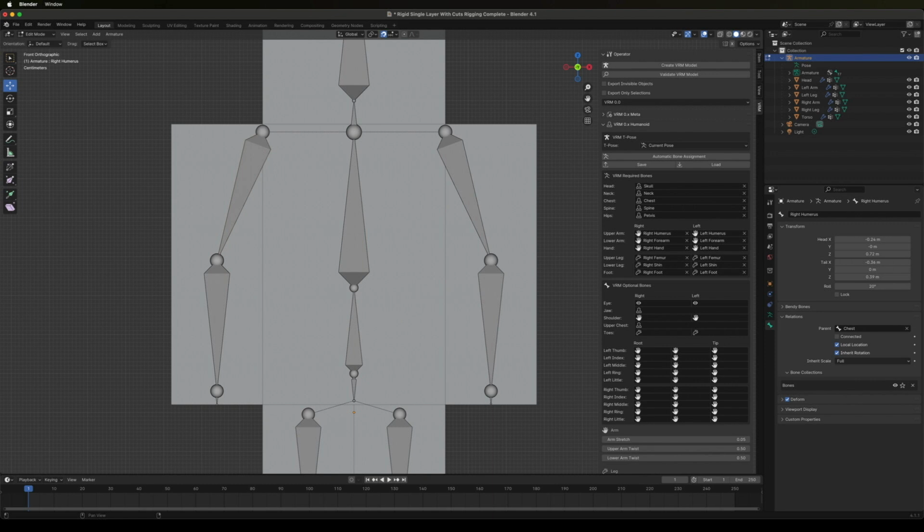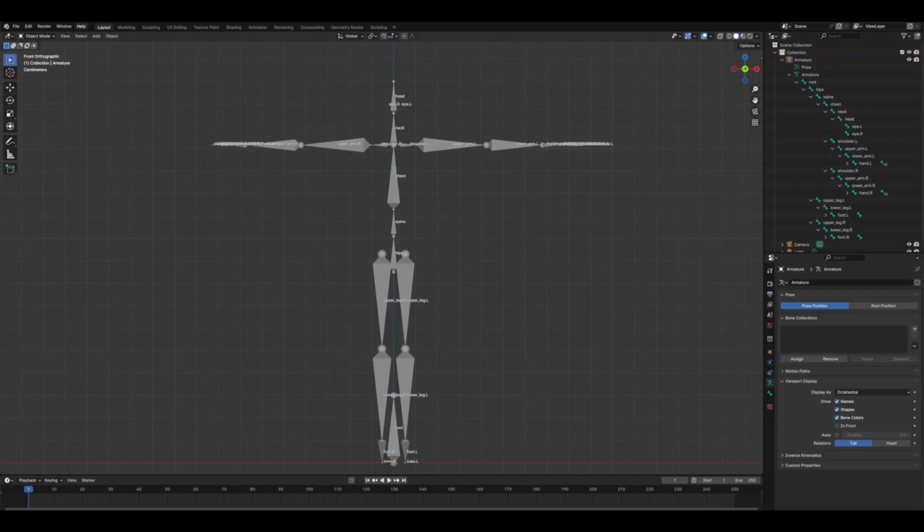If we think about the simplistic VRM humanoid model we did, as well as the natural pose of the VRM skeleton when we load it in, we'd note that they all have the same pose. If we were to load in an existing VRM character that is correctly rigged and displayed, we'd note they also have the same pose. This pose, the T-pose, is what third-party software is expecting to see when it interacts with a model. And the crossed arms pose we see with VRoid Hub is it trying to move the arms from the T down to the model's side. Since the arms began at the model's side, it ends up moving them into a crossed arm pose.